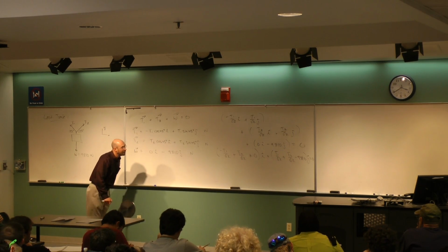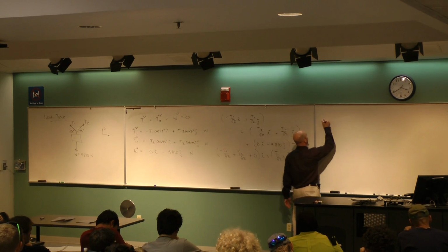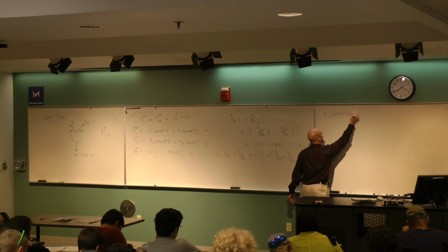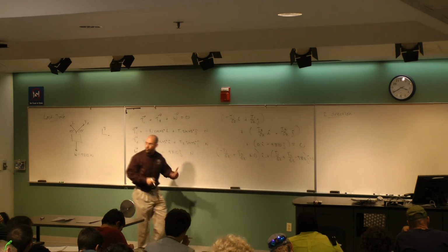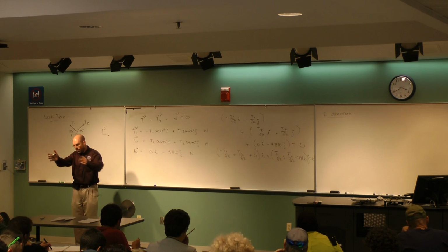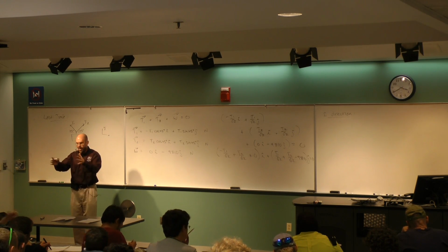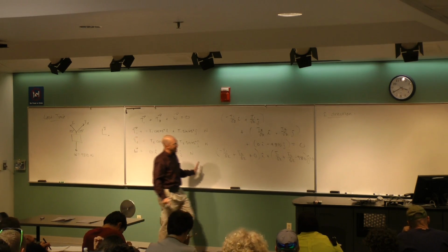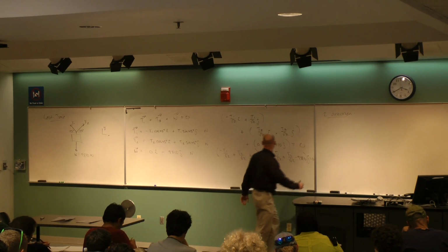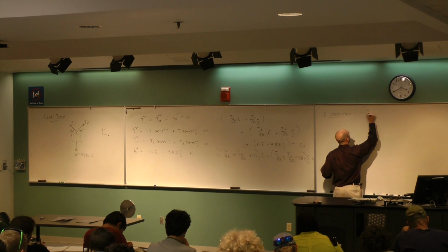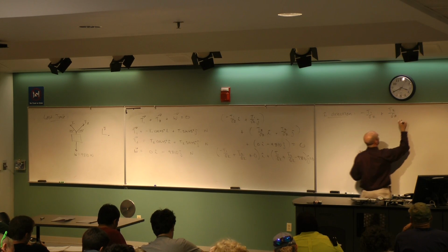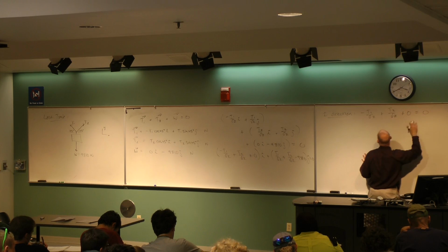At this point you reach what you would typically start with in a high school physics problem: let's look at the x direction, and let's look at the y direction. Here, the math tells you that's what you have to do. The i has to be 0. So in the i direction, minus T1 divided by root 2 plus T2 divided by root 2, plus 0, has to be 0.